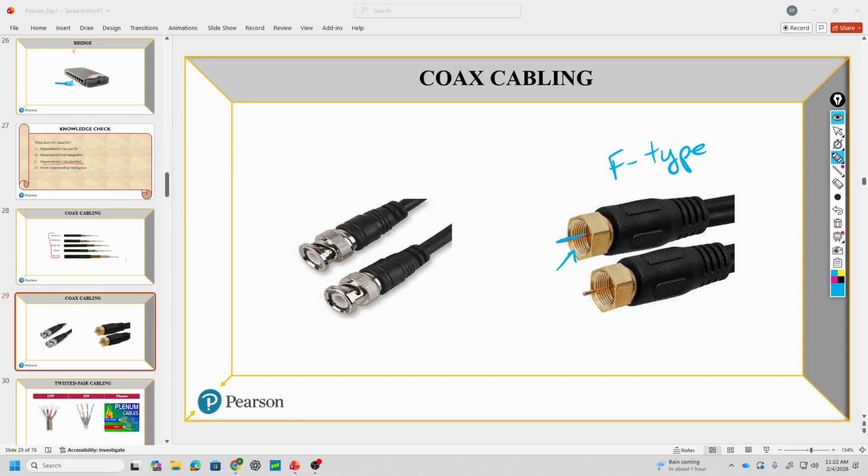That cable, when it's being built, if that copper coming out is too short, it won't get a really good connection. If it's too long, it doesn't want to tighten down right. Again, you don't get a right connection. You guys have probably all experienced this where you weren't getting a good connection. If somebody walked up there and just touched the cable on the back of the TV for a minute, it'd be like perfect reception. It'd be like, hey, don't move, stay right there, right? Because the cable wasn't necessarily built right.